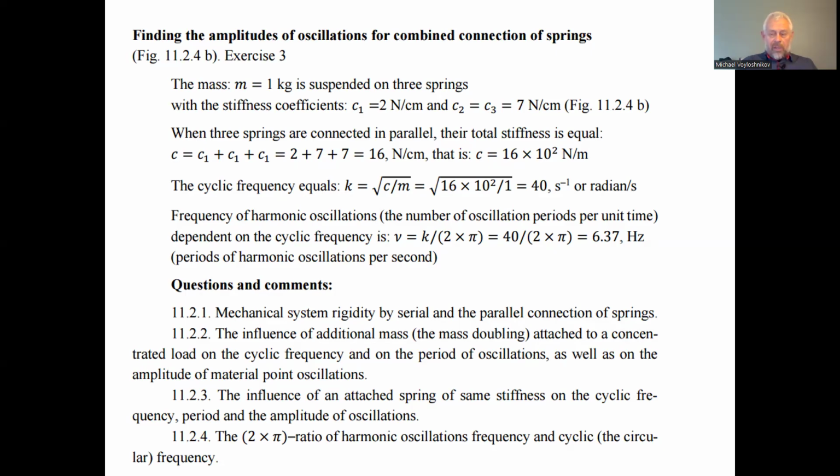The period of the oscillation reduces in the same proportion, as the stiffness of the parallel connection of springs is bigger than the stiffness of just one spring. We consider the square root proportion. And the amplitude of the oscillation of the suspension reduces in proportion to the square root of the stiffness of the suspension of a definite number of springs connected in parallel.